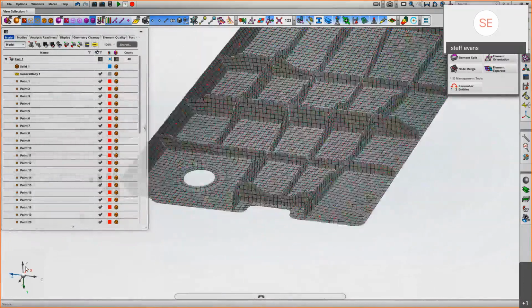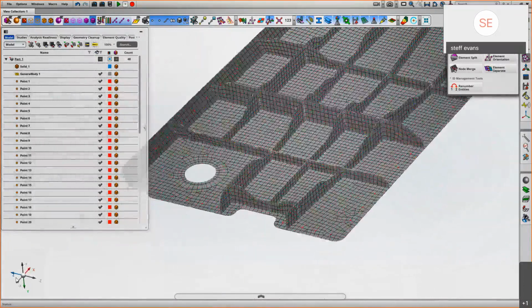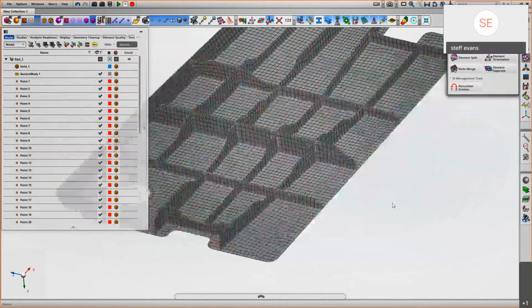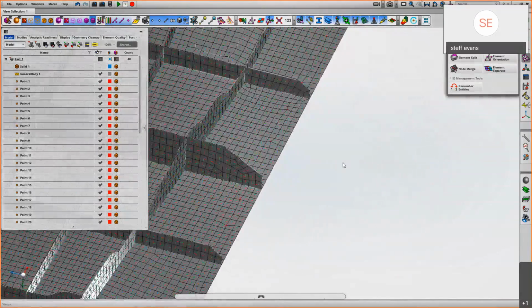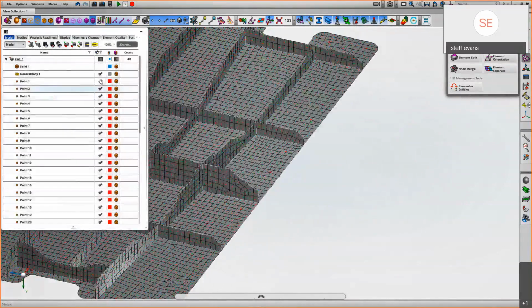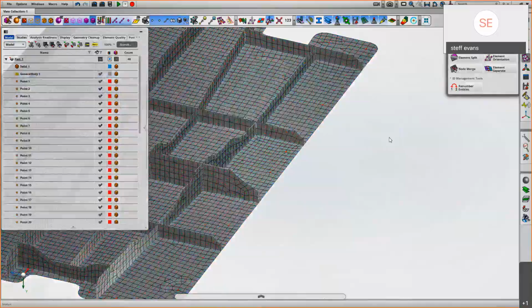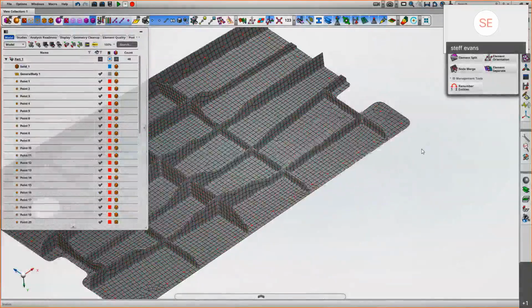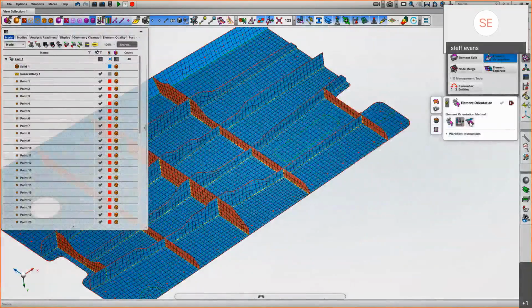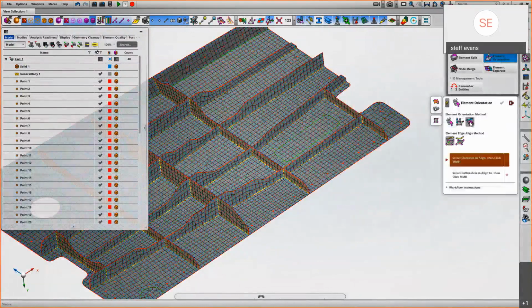Okay, in the bottom left-hand corner, the global axis is always shown in red, green, and blue. So if you're unsure which is which, if you look at the global axis, it'll give you the XYZ annotation. Obviously, if this model had XYZ written all over it as well, then you wouldn't see a lot. But what we can do is align the X direction with a vector, or in fact, we can do that with an edge.